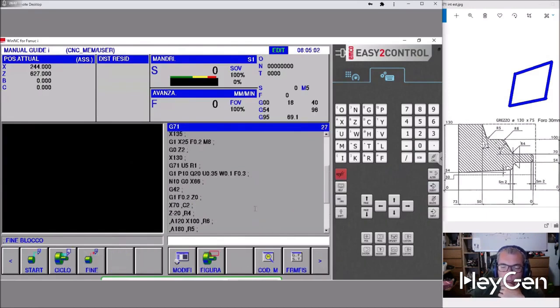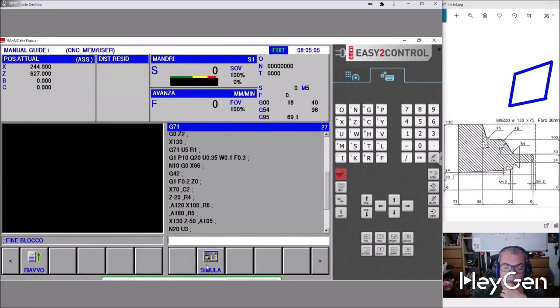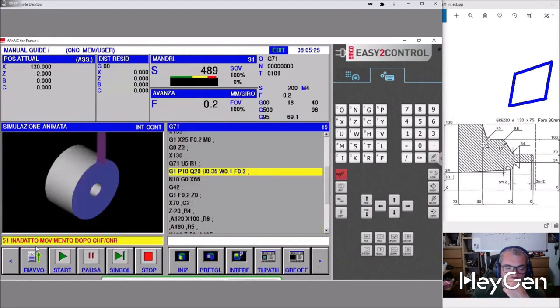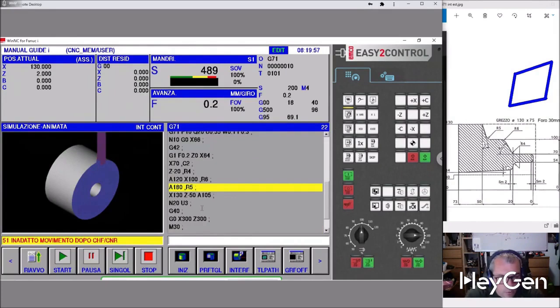These errors can happen due to various reasons, such as incorrect input or misalignment. Simulate. Let's rotate the piece according to our viewpoint, so ISO, X, and Z in this direction, which helps us visualize the process better. Let's restart the program and give it the start for the movement, ensuring everything is set correctly. CHFR, which reminds me of the limit, is a crucial factor to consider as it defines the feed rate limit, ensuring the machine operates within safe parameters.